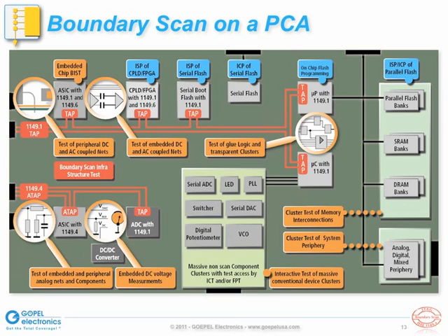Connections between a boundary scan device to a memory device, such as an SRAM or DRAM, can be tested as part of a memory cluster test or memory access test. Essentially, certain addresses of the memory are written to with certain data patterns and then read back under control of boundary scan I/O pins connected to the memory's address, data, and control bus.